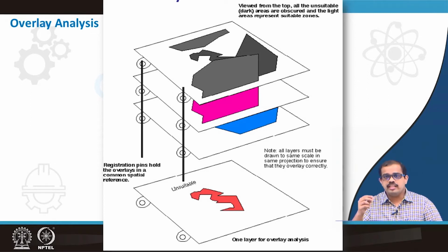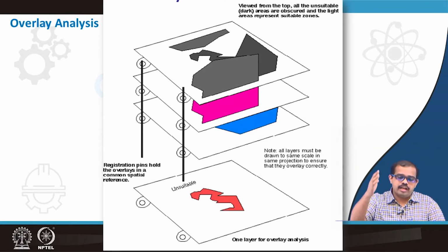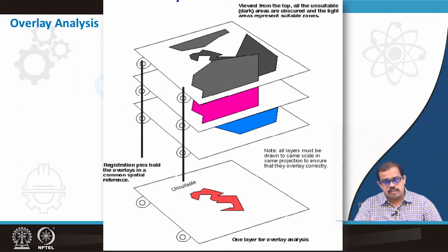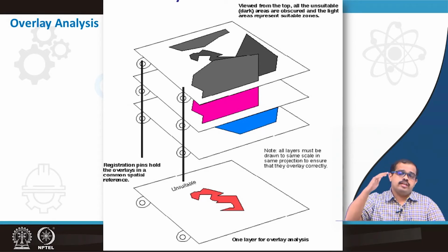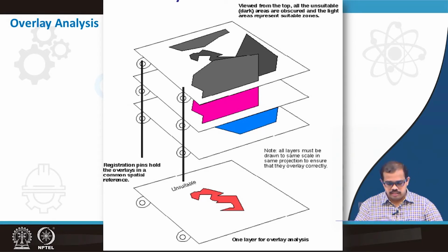So, that is one example that I have just mentioned. You can have any number of layers, any number of quantities, but these layers have to be utilized in analysis. For example, if you are using an economic layer in your urban floods, that gives you a different angle of analysis, but it may be useful for a certain section of people who are looking at your model. It may not be useful for many sections of people who are looking at your model. So, the amount of data that is necessary, the same data you will use for different kinds of analysis. That is why overlay analysis is extremely useful in GIS.